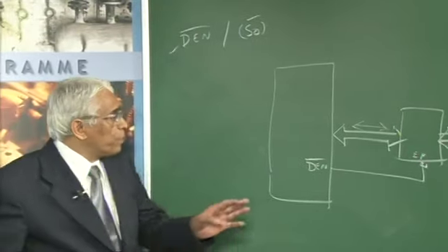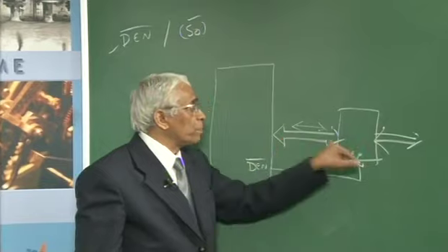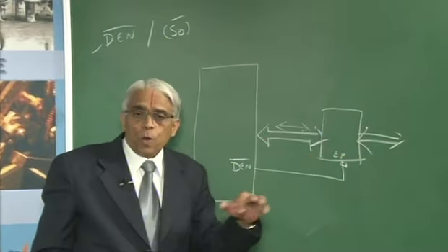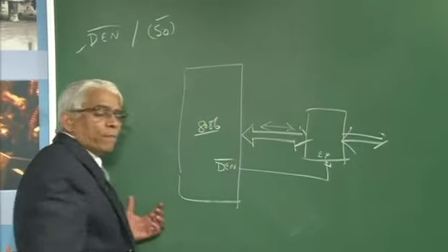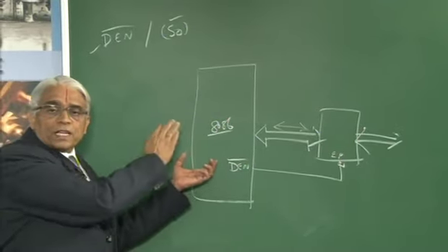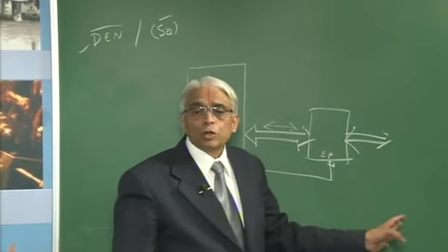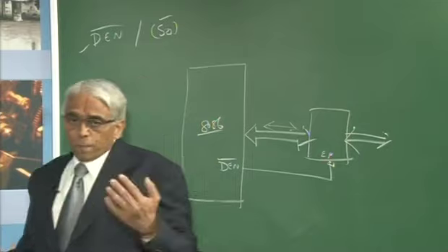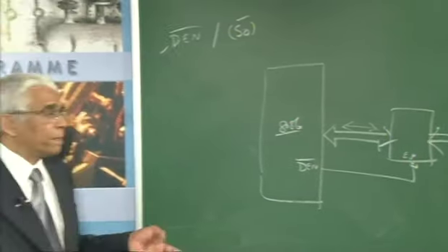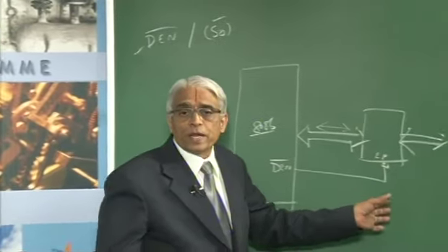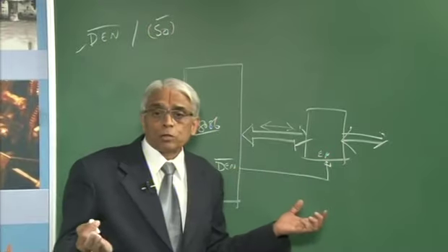Now, we have an important point to note. Why do you require a separate chip, especially for the bus to transfer or receive? The microprocessor is a very powerful and delicate device, and we think about a lot of external devices that are going to be connected. It can be power devices like a stepper motor, or something like a relay switch, where one side of the relay is connected to the microprocessor and the other part is connected to the power supply.